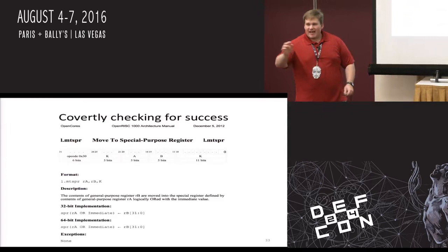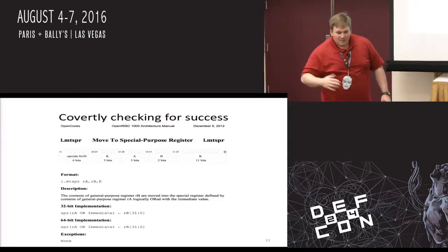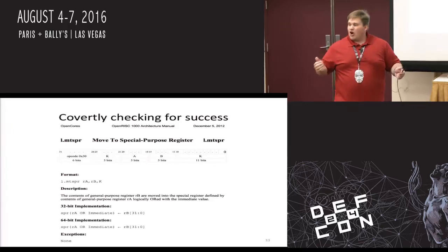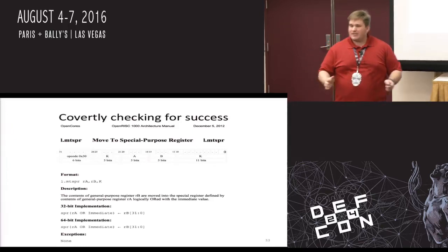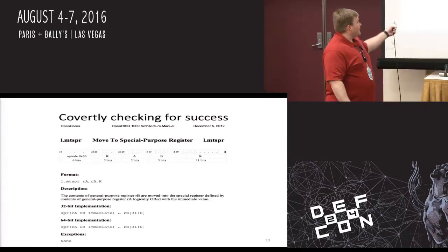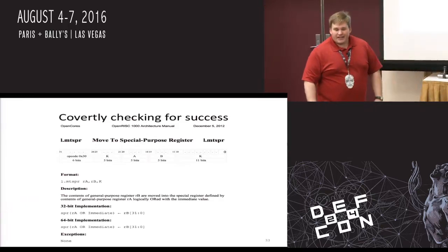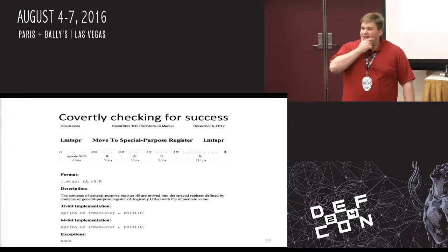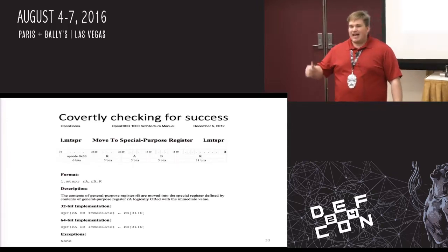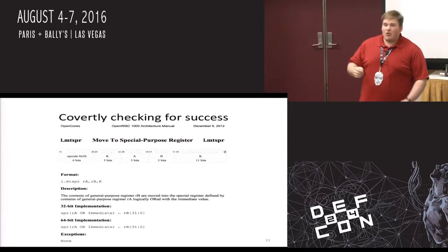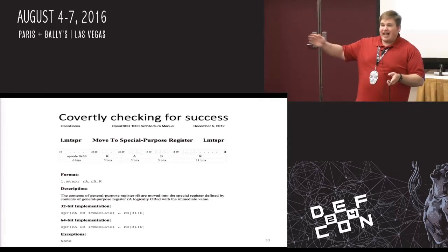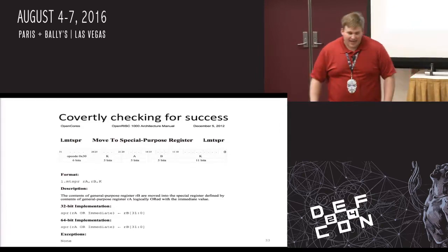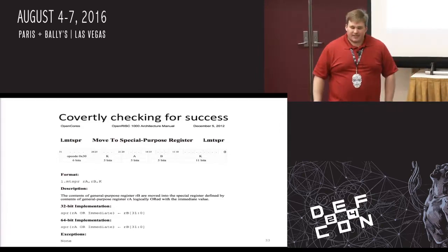So for some of you from x86 land, this is going to be a little different. We implement this on the OR1200, which is an open source RISC processor. Here's a snapshot of the instruction set specification page for it. And really the next question is, okay, I have my attack, I know what wire I'm attacking, I know how to trigger it. But how do I know when I can spend cycles on escalating my hardware attack to software instead of just trying to trigger my hardware attack? And this is called checking for success.